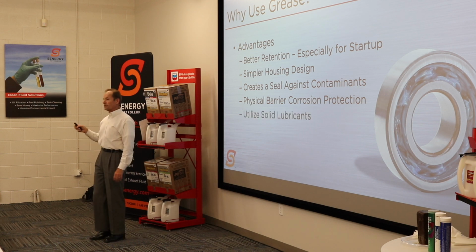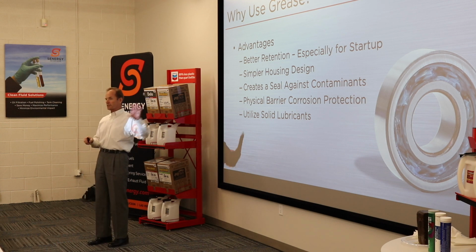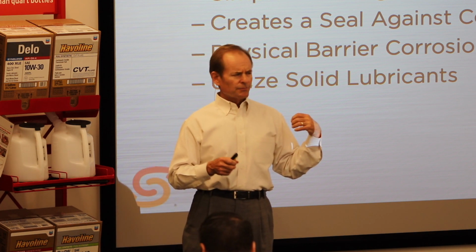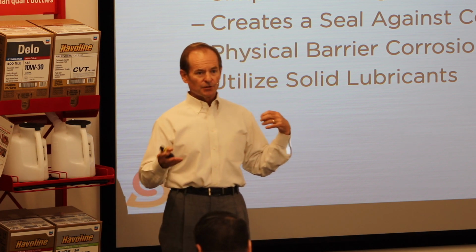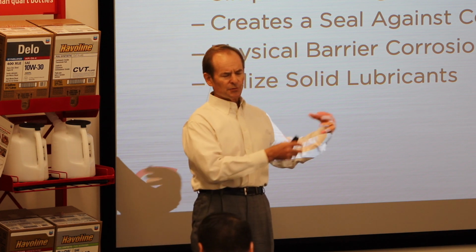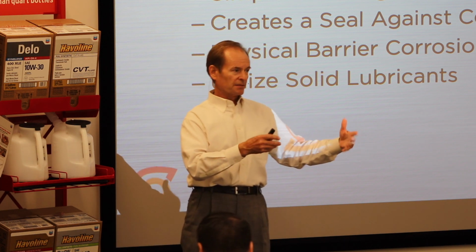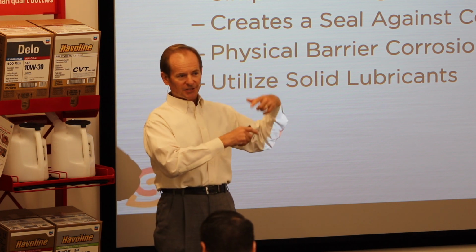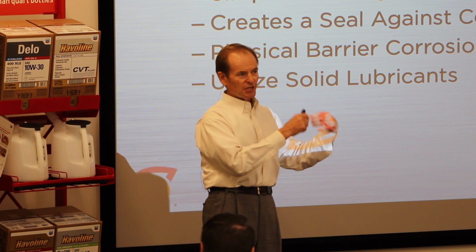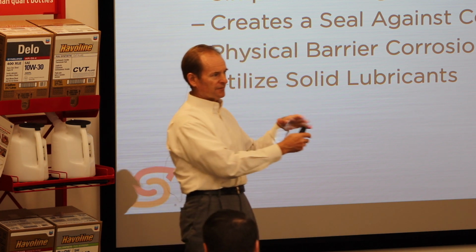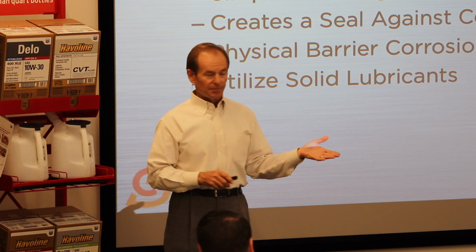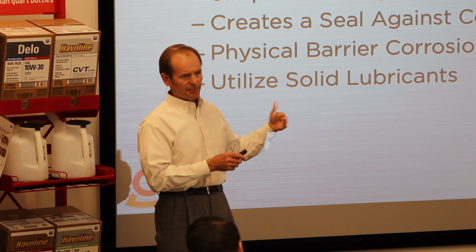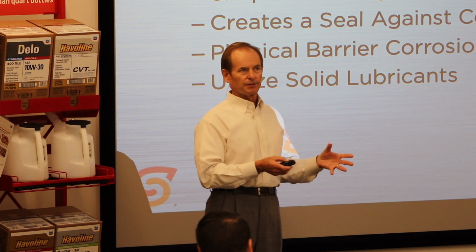And greases can allow you to utilize solid lubricants. I've got a slide later on where we'll talk about solid lubricants and how they work. By solid lubricants I mean something like graphite or moly, molybdenum. If you put them in an oil, and some people try this, the biggest problem is that they sink to the bottom of the oil. You have to continuously agitate them or have it in motion in order to get your moly suspended enough that it finds its way eventually onto bearing surfaces or between gear teeth. So nobody really effectively does a good job of putting solid lubricants inside of an oil.